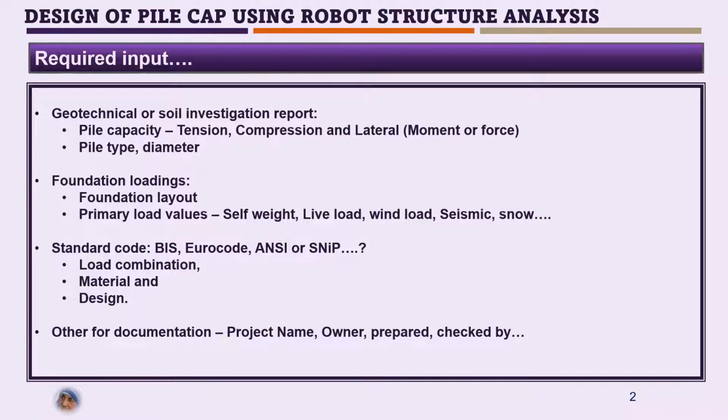The inputs required are the geotechnical or soil investigation report, comprising pile capacity in tension, compression and lateral forces, pile type and diameter, and foundation loadings, which are defined through the foundation layout and primary load values such as self weight, live load, wind load, seismic, snow or any other loads.